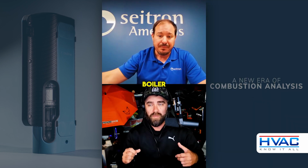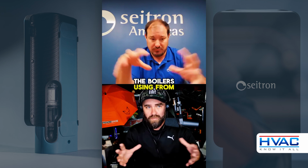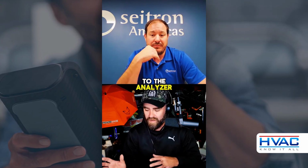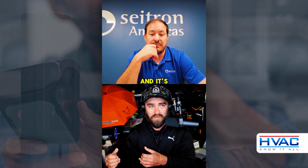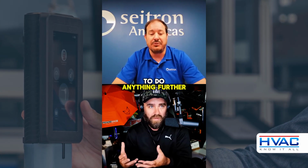Let me set this one up for you, and let's just clarify. So if we're working on an atmospheric boiler, it's drawing all the air that the boiler's using from the boiler room, right? There's no further work to be done to the analyzer to make sure we have a proper efficiency, because it's got a sensor on the analyzer and it's comparing the stack to the room temperature, right? So we don't need to do anything further there, right?